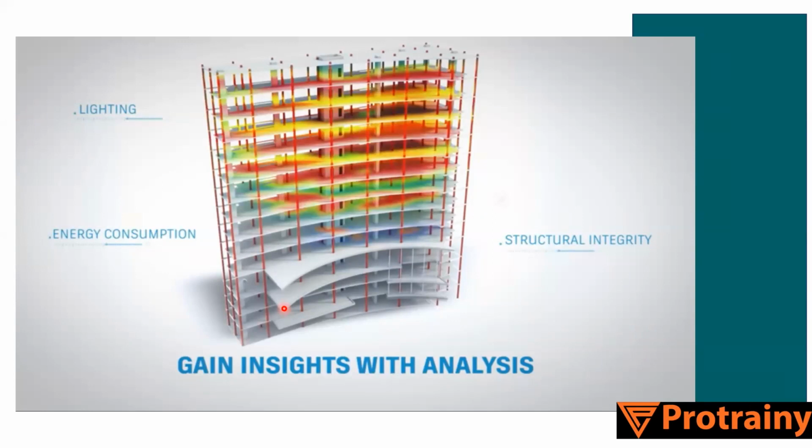And how? Let me tell you about structural integrity analysis, which is very important for us. Starting with the ground floor, the column and beam layout is there, there are so many shafts and we are designing that. But when we have created the whole structure altogether, then we are able to analyze that the column sizes going downwards carry the maximum load, and we can decrease the size of the column gradually going upwards.